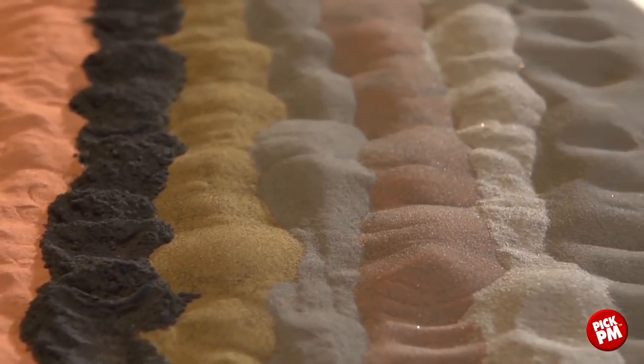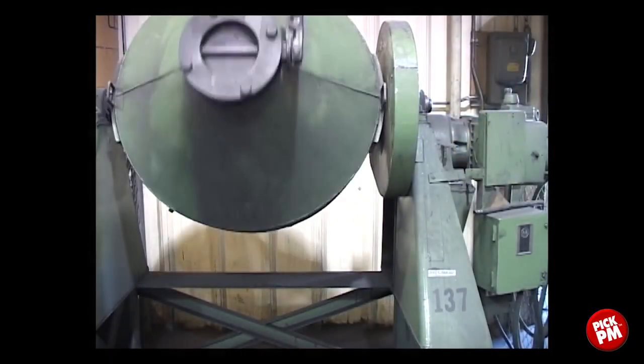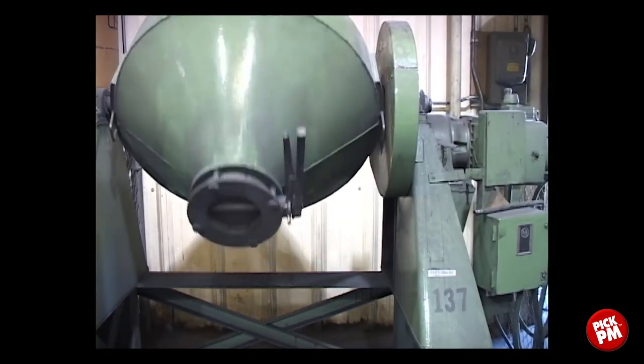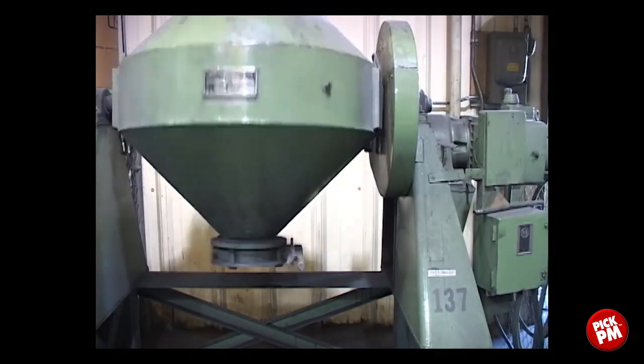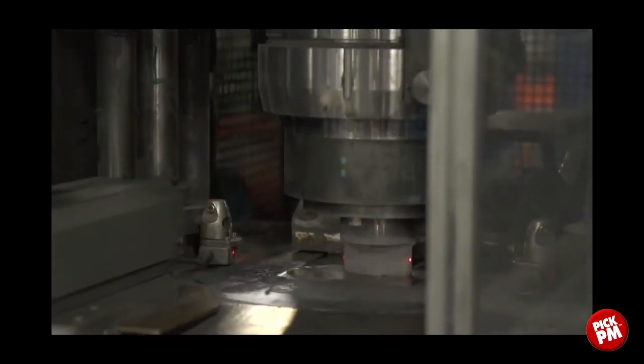Powder is prepared for production through a process of blending and mixing. Elemental or partially alloyed or pre-alloyed metal powders are mixed with lubricants and other alloying materials such as copper, nickel, graphites, and lubricants for compacting. Blending is a thorough intermingling of powders of the same nominal composition, such as two different types of iron powder. Mixing is the thorough intermingling of powders of two or more materials, such as iron and copper or iron and nickel. After mixing, the powder is then brought to the compacting press.